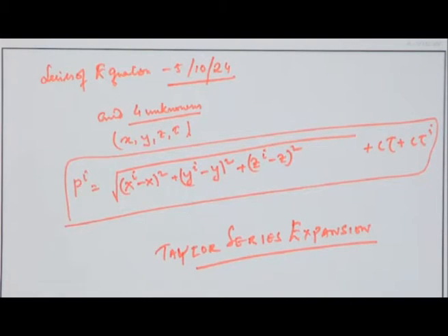So what is happening is, there is observed and there is model, and there is noise. We solve the point positioning problem by first linearizing the pseudo range observation equations and then using familiar methods of least square analysis. As I told you, we will have a least square analysis to solve it. For completeness, we summarize the linearization procedure and the development of least square methods specifically for the GPS point positioning problem. First, we assume we can write the actual observation to be the sum of the model plus an error term, which is noise.